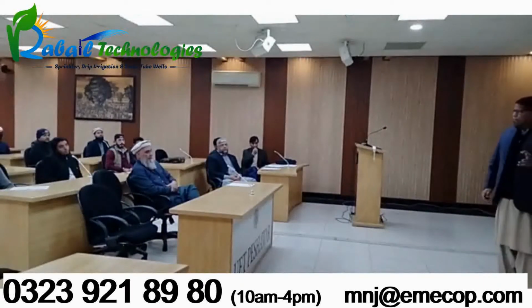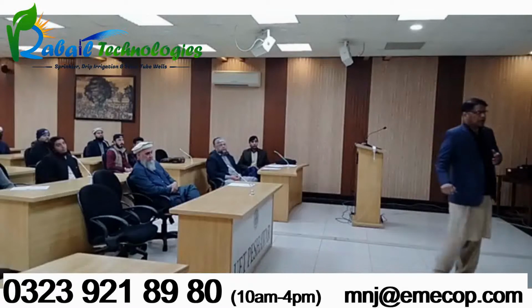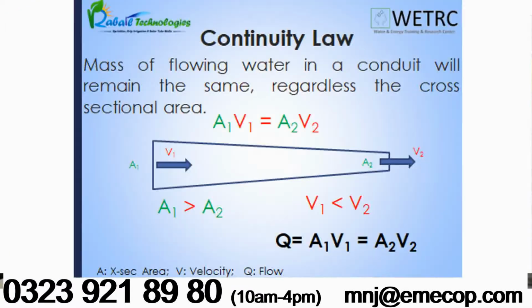Continuity law is very simple: the amount of fluid entering here will remain the same regardless of the cross-sectional area. Whatever fluid enters here, for example a flow of 10 cubic meters per hour, from A2, the outlet of that conduit, it must also be 10 cubic meters per hour, regardless of the area, whether it is higher or lower.